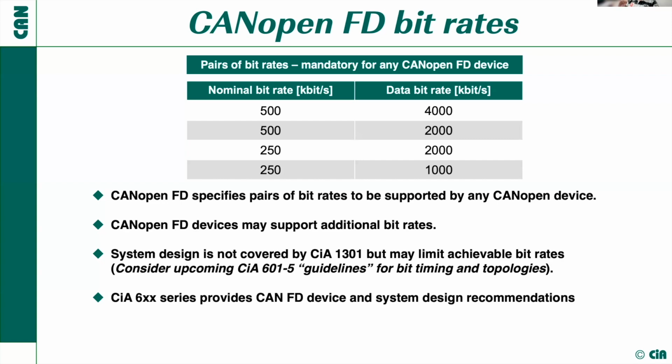And on top of that, we are currently thinking in the IG CAN-OpenFD how we can particularly make use of CAN-OpenFD in topologies or in networks where we are not that keen on high data throughput, but on a lengthened data field, and maybe a large topology would avoid high data rates, high communication speeds. And nevertheless, we want to make use of CAN-FD and CAN-OpenFD, and how you can do this in the best way. We are currently specifying this in the CAN-OpenFD group together with lower layer experts. So if you're interested, I'd like to invite you to this group.